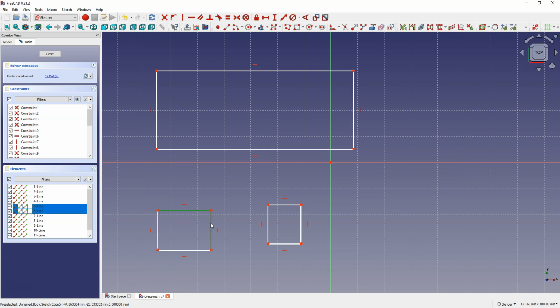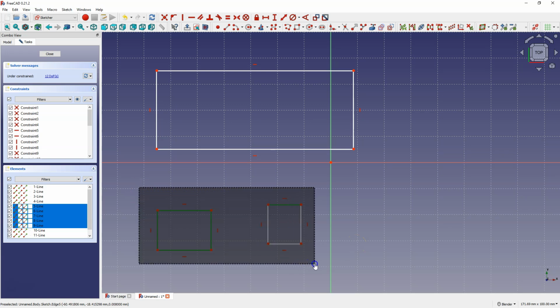delete key, and we can select the geometry in such a way that we simply left click on the geometry we want to delete. Here note that in the sketcher module, that is when creating a 2D sketch, as we point to the geometry, we don't have to hold down the control key. We simply left click on the geometries we want to select, and we can do it just with the left mouse button, or we can use the selection window and simply press the left mouse button to drag over the geometries we want to select.